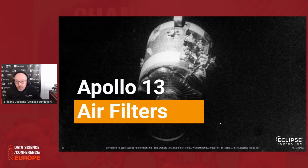And well, the lunar module wasn't built for that at all. And one of the problems there with the lunar module is that there weren't enough air filters in it to be able to serve a crew of 3 for 2 or 3 days. Okay, it wasn't designed for that. They had just enough air filters to do their little moonwalk and get back, and after that the command module was supposed to take care of stuff. The problem being that the shape of the air filters in the command module was different from what they had in the lunar module, and we see that on the next slide.